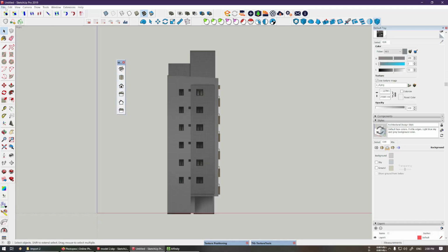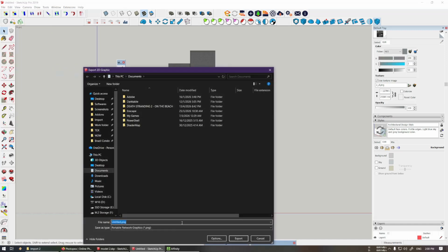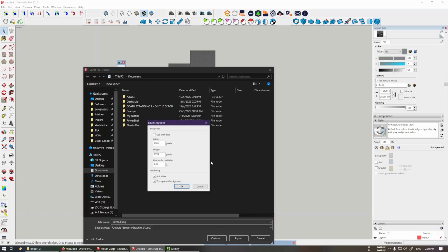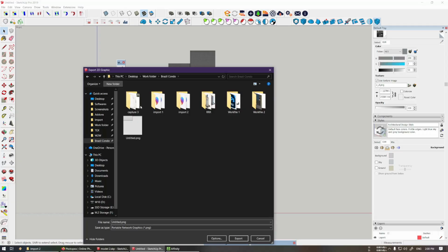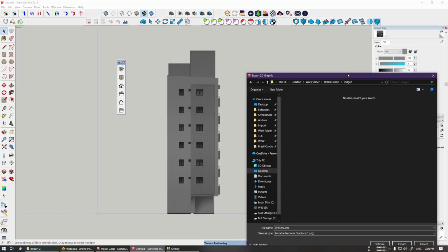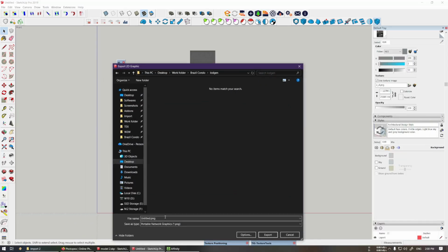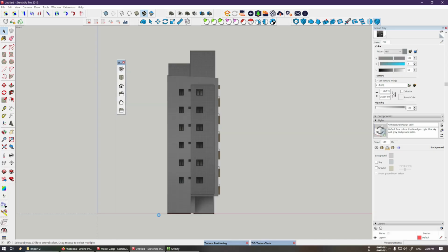After that, what you do is simply File, Export to Graphic, and set a hotkey for that. PNG, Options, set a high resolution size, anti-alias, and transparent background. Export this somewhere. Let's say make a folder called LotGen. This one is actually the left side, if I'm not mistaken. Left D. Put a suffix for it so you know which texture this represents.